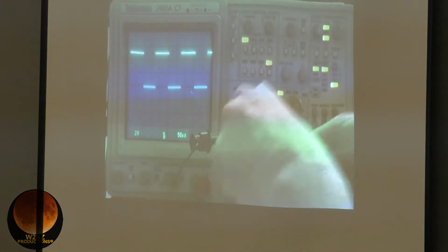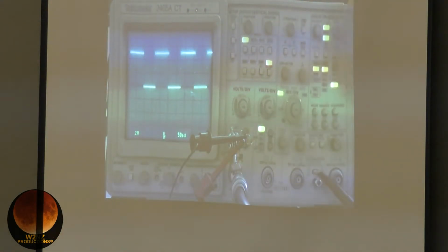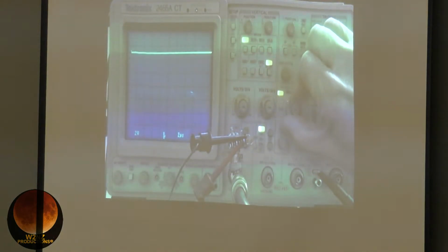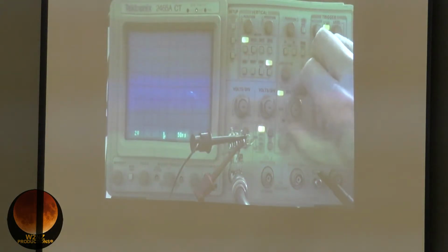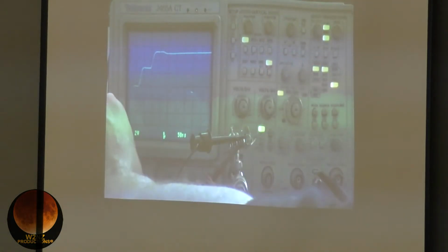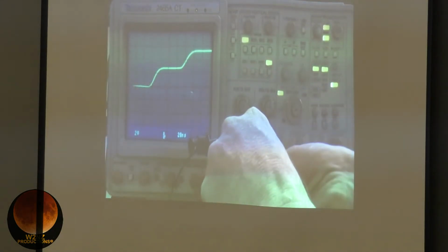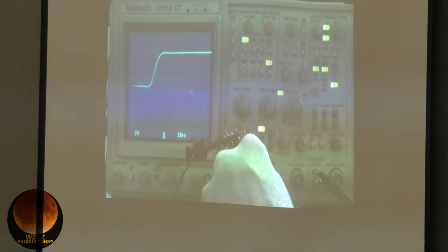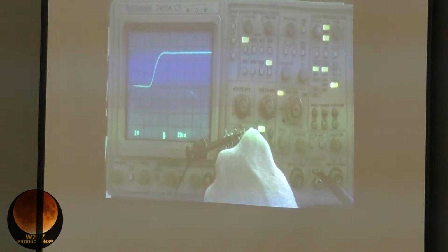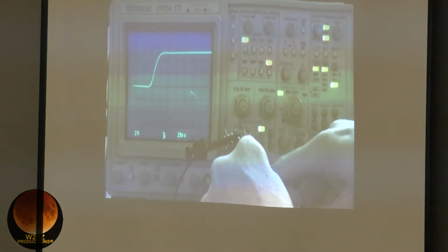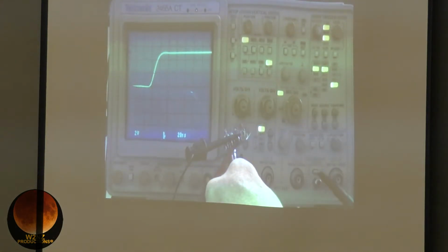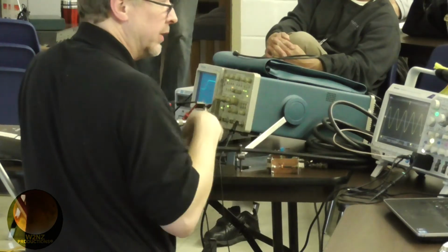Well, not a whole lot happened, right? Well, let's zoom in on this. Let's adjust my signal level here and zoom in on this. And turn the intensity up here. Look at that. Now, if I take that coax off, I'm just rising right up, right? The signal's going down to the end, reflecting, coming back from the end of this tiny little T. So it's happening essentially instantaneously.